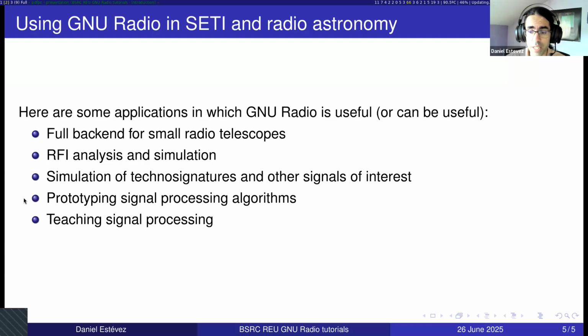Also, any kind of signal processing algorithm you have in mind, you can write it in GNU Radio. We will see that it's possible to write your own blocks by writing some Python code in some text editor. Basically it says, fill in here your math operations in Python. So if you are thinking of doing some signal processing, and maybe you are doing that with a Python script or with a Jupyter notebook, or something similar, but you want to go a bit beyond that and you want to be able to run that in real time, connected to a radio or to process some files, GNU Radio can be a good platform for that.